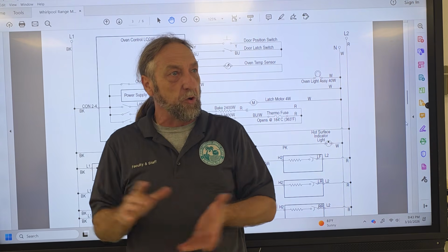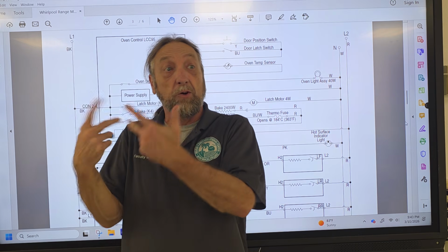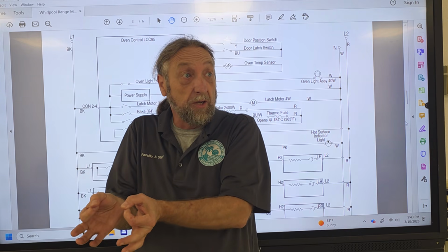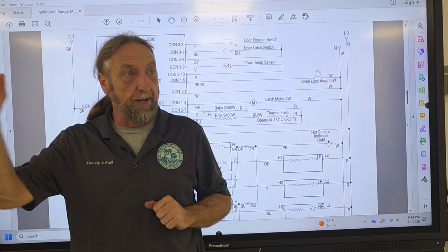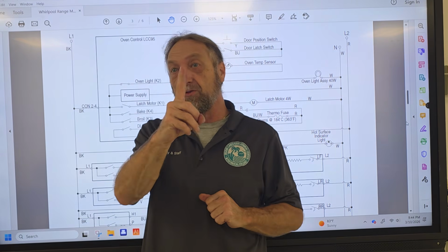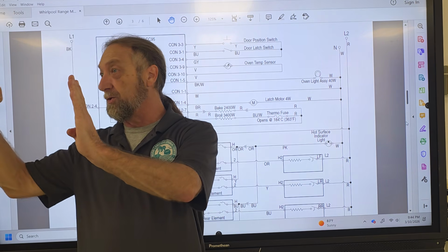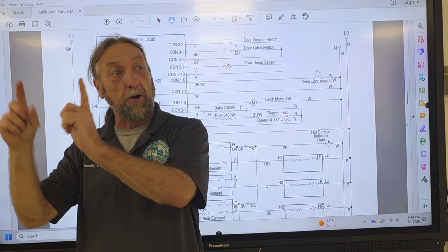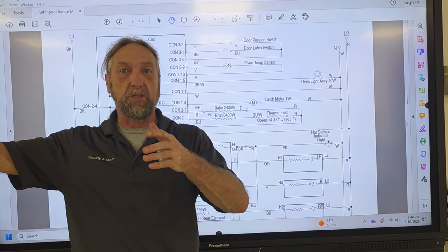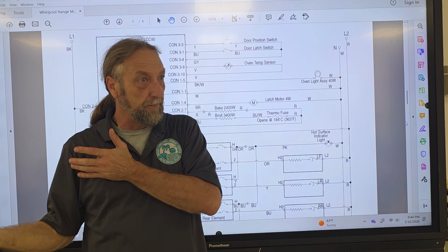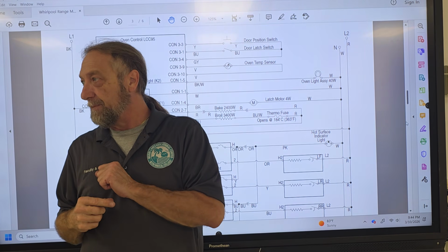If all four of her elements are doing the same thing, well, the first thing we need to know is how much power that element is producing. And in order to do it, we need to know the voltage. So we have the voltage, the amperage, and the wattage. Power, P, equals I times E, which is current and voltage. So you take the voltage, 208, you measure the current going through the wire, and you multiply them, and you get the actual wattage output. So if you had 208 times 10 amps, that would be what? 2080, right? P equals I times E.